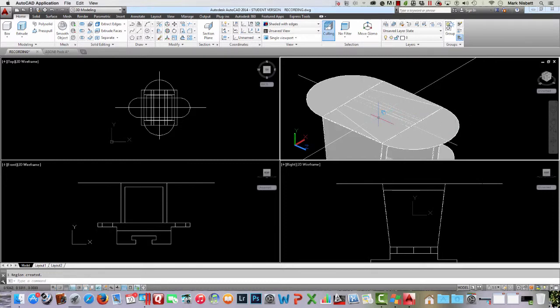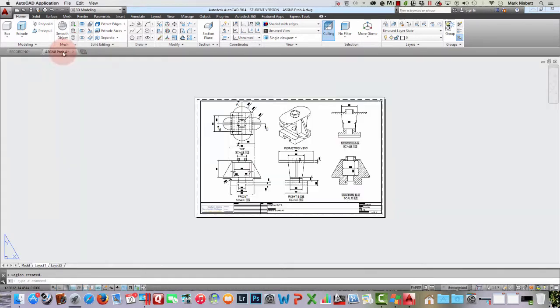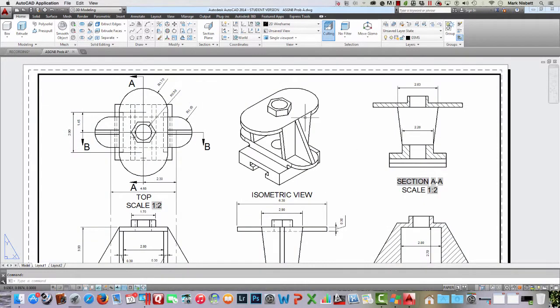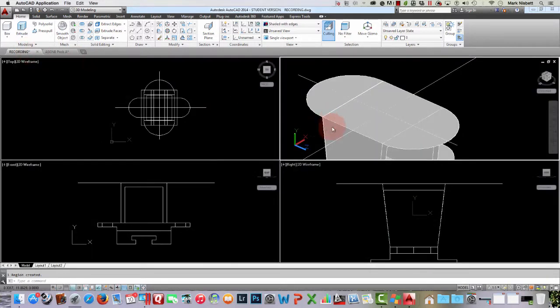This surface here is shared by the top. If you look at this isometric, you can see that here. So we're on this top plane, so we need to extend it down and union the top of this to the other part. So with that said, we're going to just go ahead and extrude this down, and it should be 0.3,